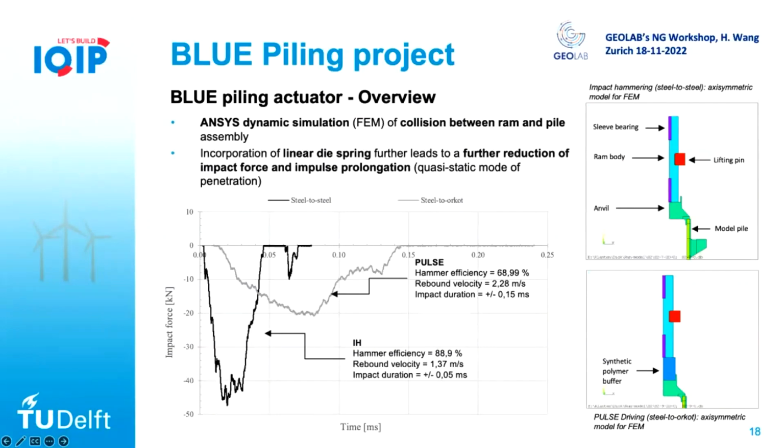Yeah, thank you. Indeed. One addition about the gray curve that we see here. We see that the integral, basically the energy, between the 2 piles in this case is comparable, but the company IHC has foreseen to increase the energy by a factor of maybe 1 order of magnitude, while still prolonging the pulse to about 200 milliseconds, so around 20 times more than the impact hammer pulse. So you maintain the pile in compression, which is the concept of Statnamic. Exactly. Rob at IHC was the Statnamic converter, so we just converted it to the pile. Yeah, indeed.